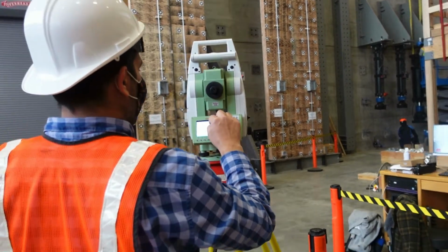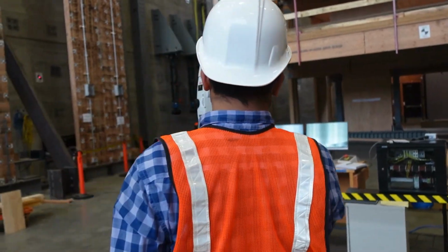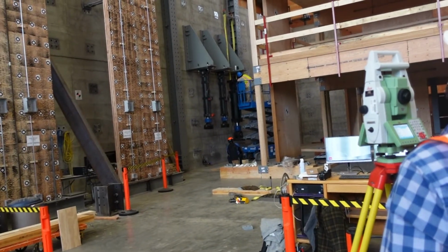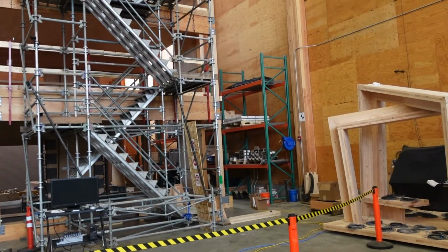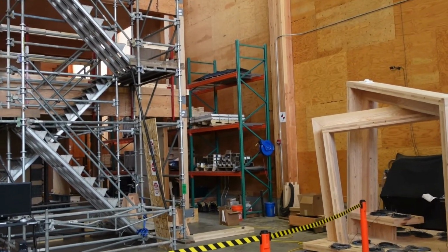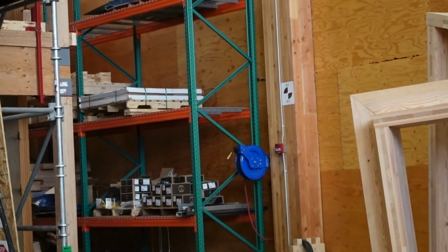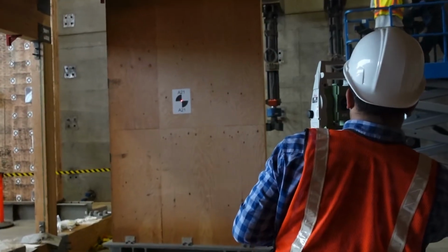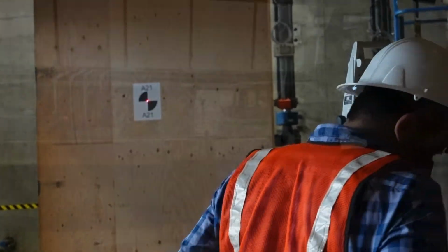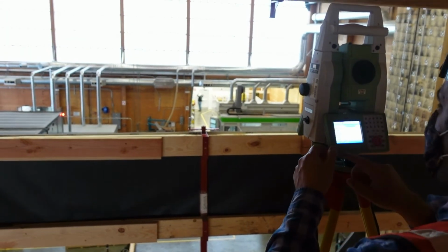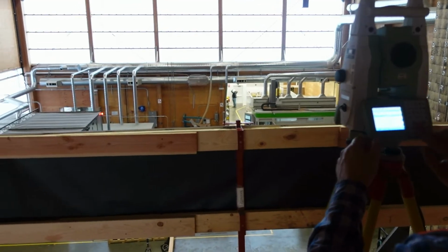An important quality control technique in the survey is letting the robot find previously registered points on its own. In this part you can see how it looks for point A1, being as accurate as expected. The total station was then moved inside the building to have a complete survey of every target, finishing this part of the process.